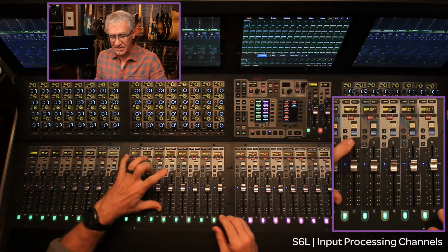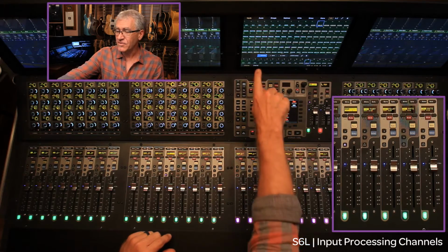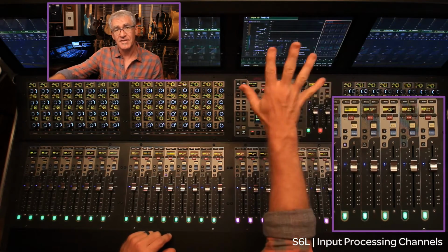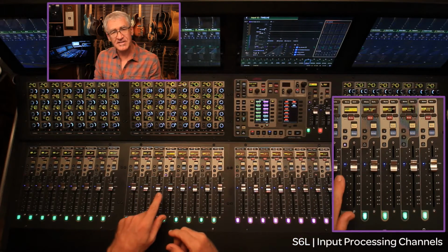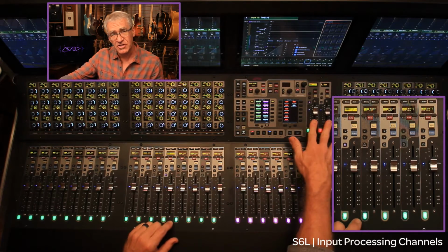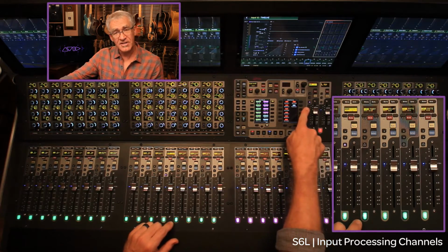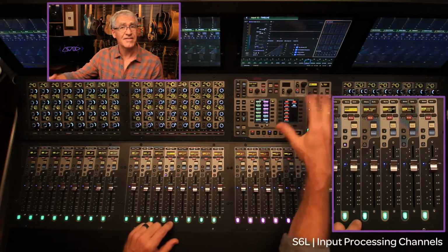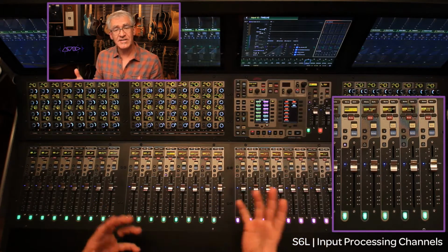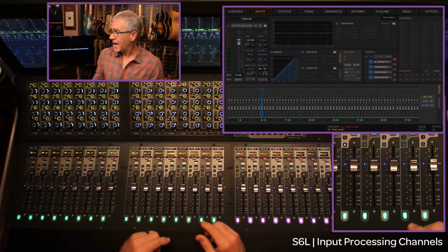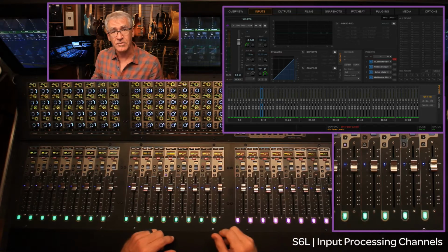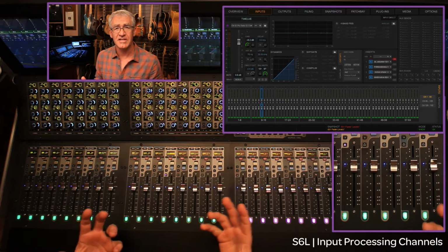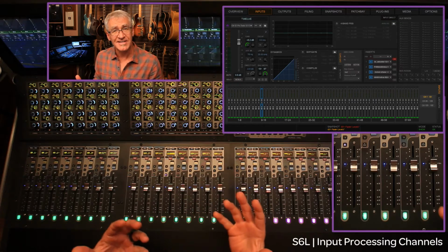So, for instance, if I press the attention button once, and I have channel chosen in the center of the console on the center CTM, notice it brings up an exploded view of that channel there. Likewise, a single press of the attention button, if I have a flex channel set up in my master section, will attention that channel to the flex channel, and I can lock it there or do whatever I want to do with it. Likewise, if I double tap that attention button, I can now bring it up on the external screen on the venue software there for an even more detailed version of it, as well as all of the other fader views along with it, okay? So very similar to how select worked on our previous systems, now it's called attention, and you'll see why as we move forward here.